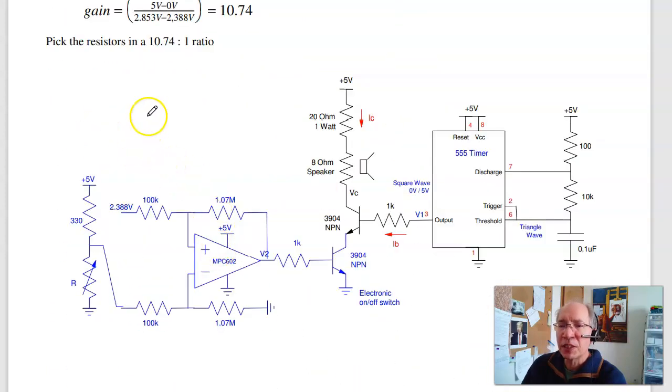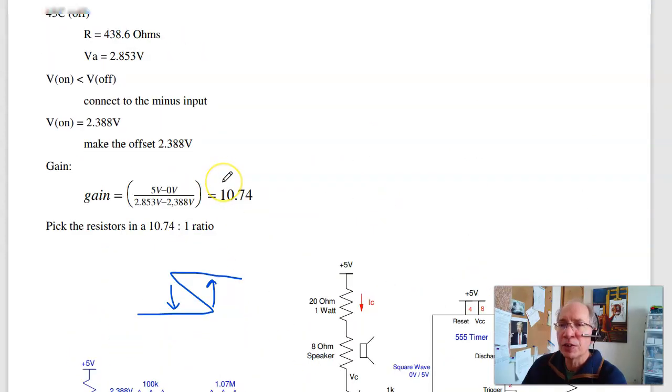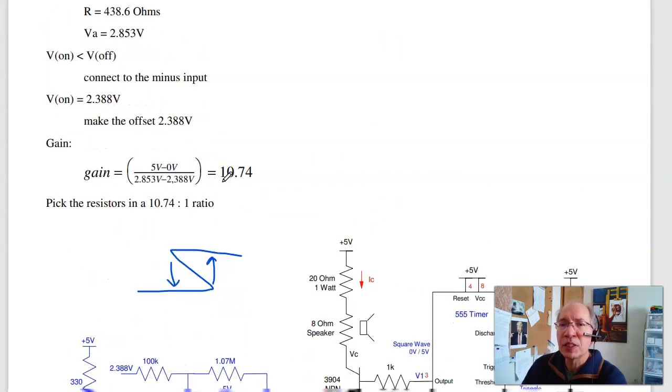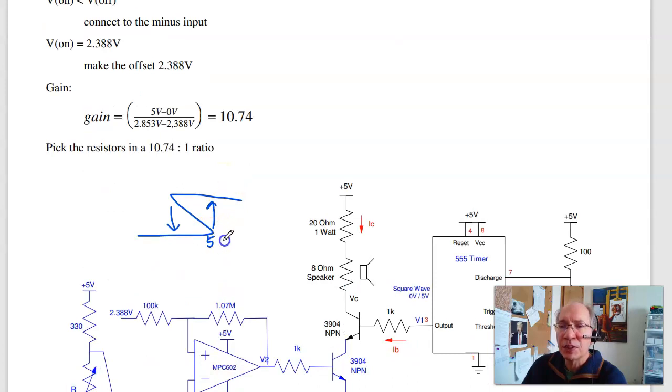That's this guy right here. What this does, in terms of temperature, is going to do this. I want to turn on at one temperature, turn off at a different one. I want the on temperature to be 55 C. Off temperature to be 45 C.